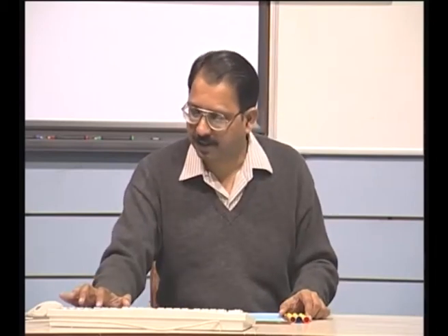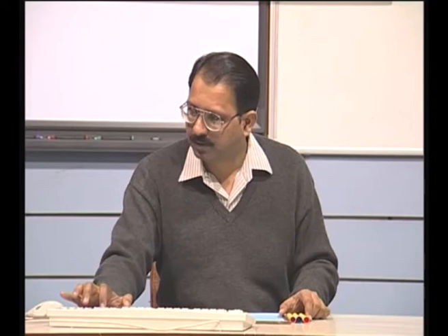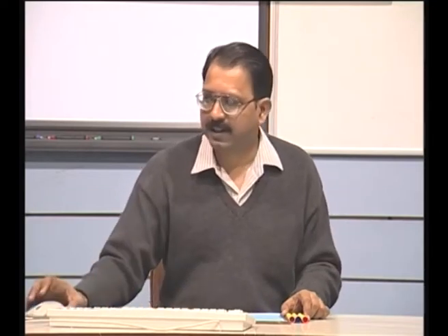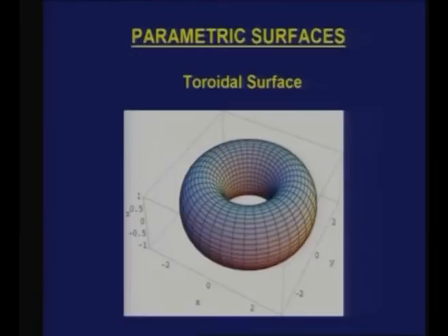Let me go back to the toroidal surface. So, how are you representing, let us say, a toroidal surface? I have an axis, and how do I obtain a toroidal surface? What is the generatrix and what is the directrix? Let us look at this. For example, these parametric directions which you are seeing, I can call it a generatrix. Then this is a directrix kind of a thing.